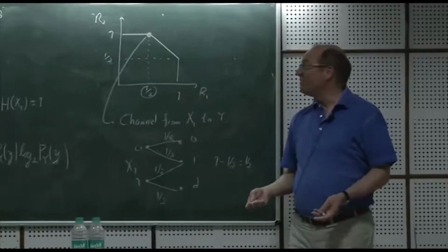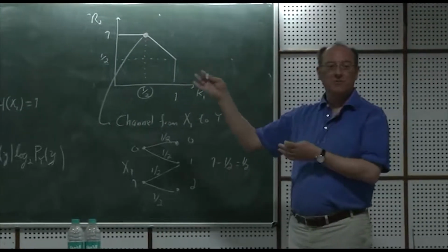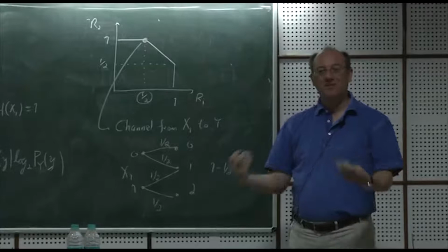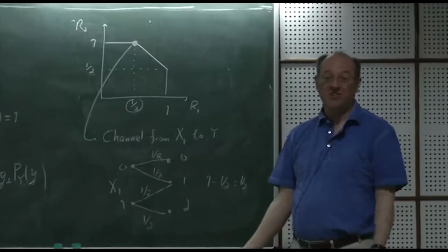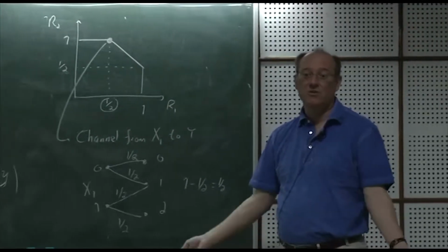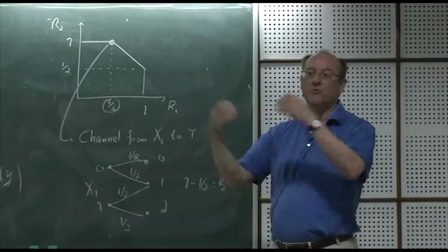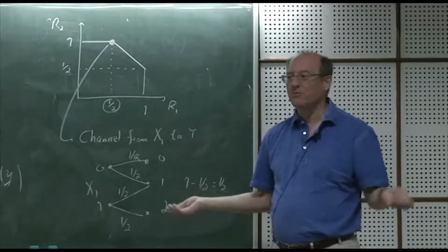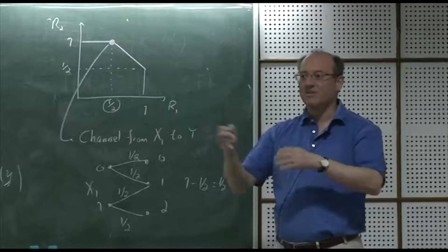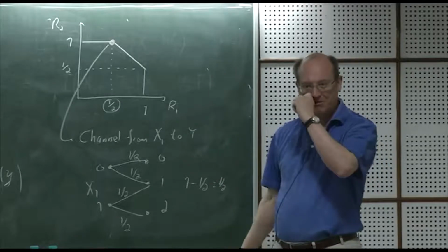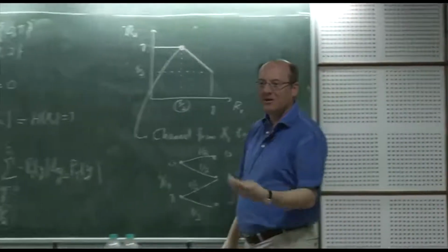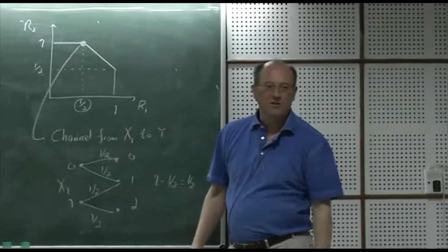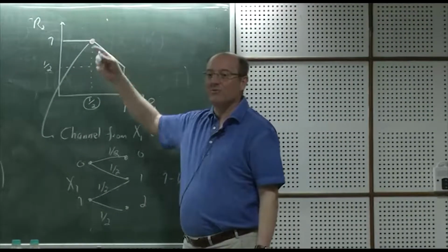So again, even though there's no noise here, because of the interference, the problem gets interesting. User 1 actually has to use a sophisticated code. LDPC code, Raptor code, Reed-Solomon style if you have large alphabets, but okay, here we don't. Here we have binary alphabets, so we have to stick to binary erasure channel correcting codes to get close to that point. So that's interesting.